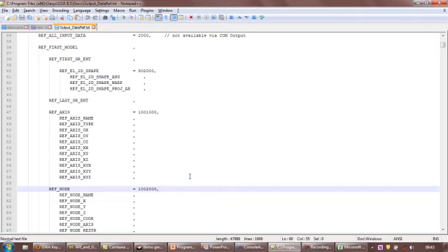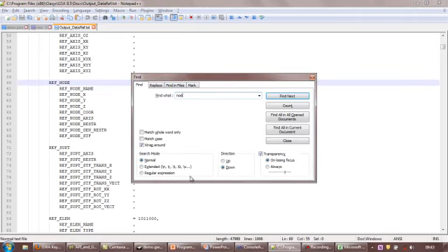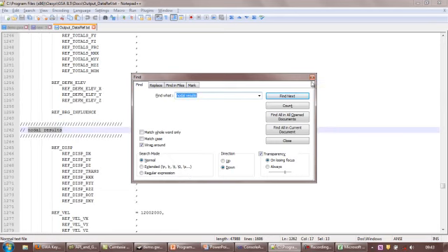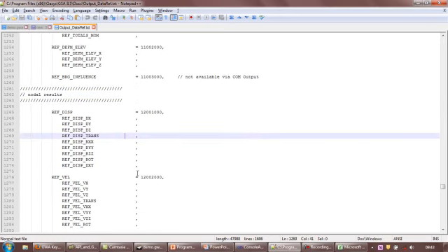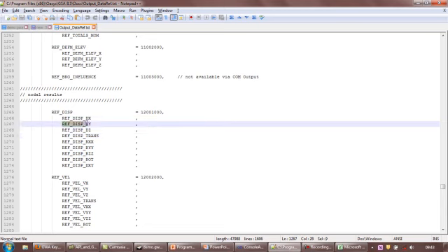So if we want nodal results, and we want the Y translation, there's a little bit of guesswork here, but the names are quite suggestive, but sometimes they're not. So disp_dy stands for Y displacement, and we can in fact cross-check this. But firstly, we need to calculate the right code.